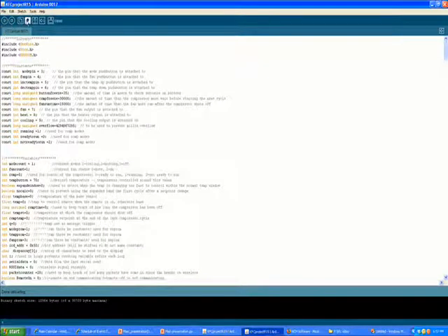The next piece of useful code is how we put the remote to sleep. As temperature change is gradual, we didn't need to continuously send data back. Instead, we sample every so often and then put the remote to sleep, thus extending battery life. After the code has been compiled, it will display how much data has been used and how much data is available. On our final version, we use only about 40%, leaving room for expansion.